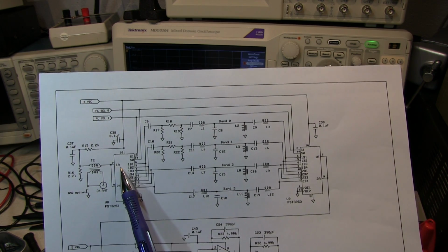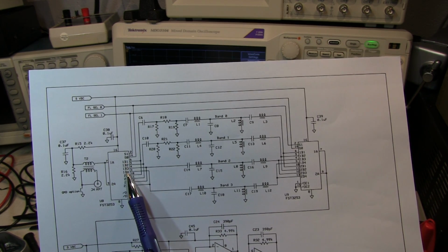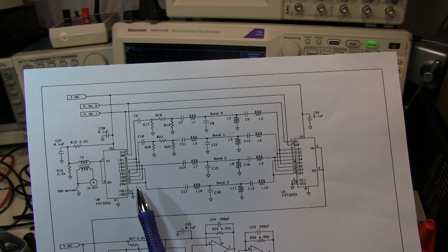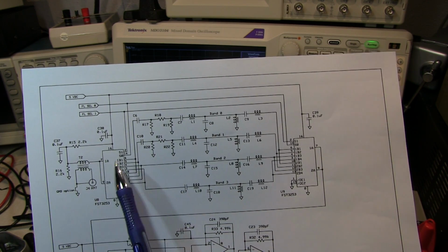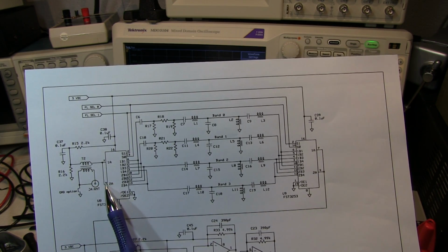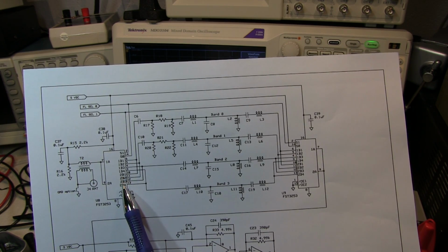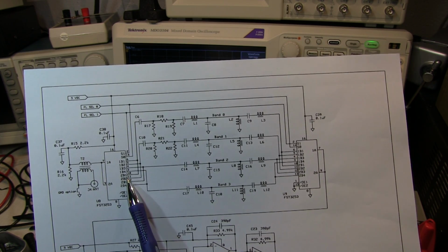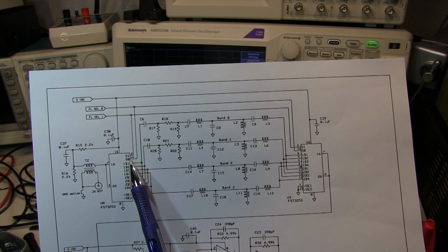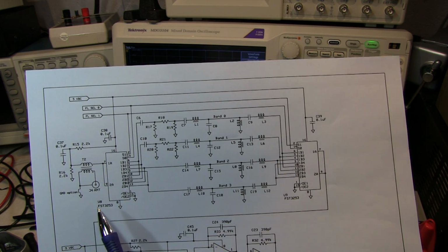So the 1A will connect to these 1B outputs 1, 2, 3, and 4, depending on the state of the switch inputs coming in, the filter select lines S0 and S1. Similarly, input number 2 on the A side will switch to outputs 1, 2, 3, and 4 on the B side. So really the selection of these 2 bits will determine which of the 4 outputs each of those go to.